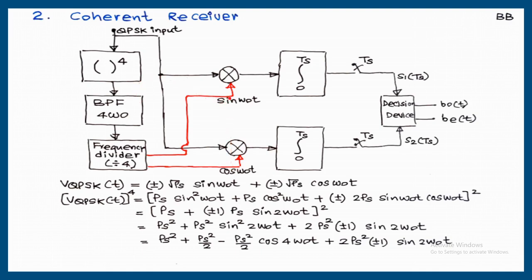These are the phase quadrature carriers regenerated from the received signal for reception. If the regenerated carriers are used for reception, then the receiver is a coherent receiver or synchronous receiver. Probability of error will be minimum, but due to this, the complexity of the receiver is maximum.